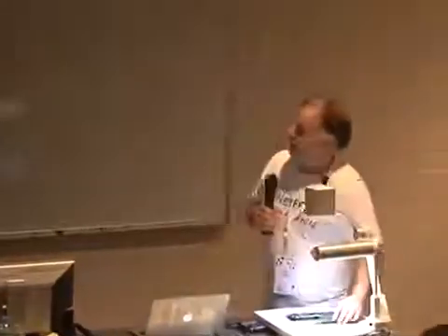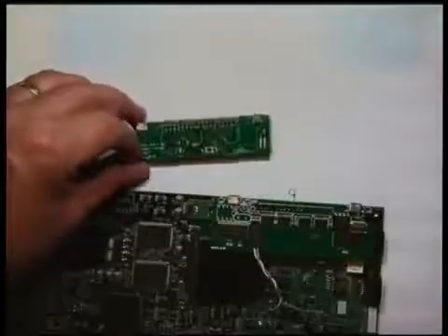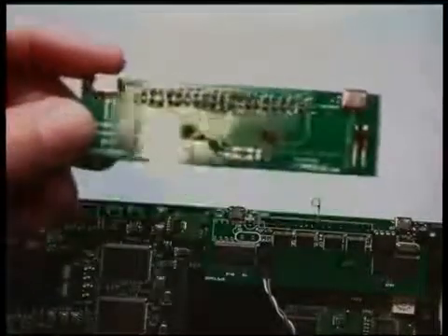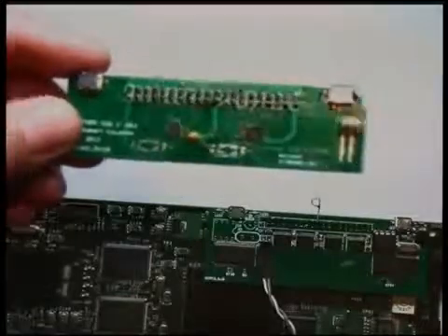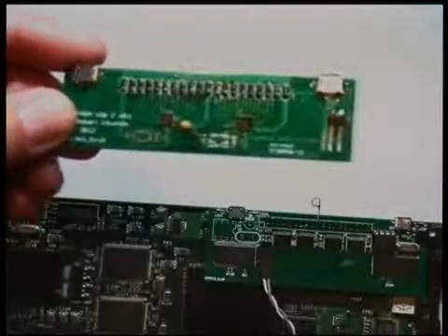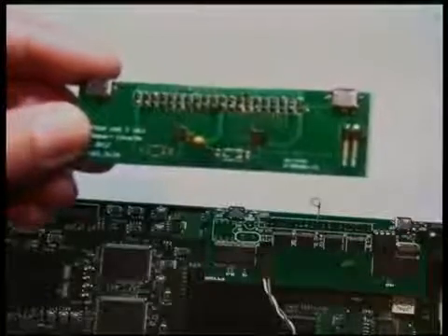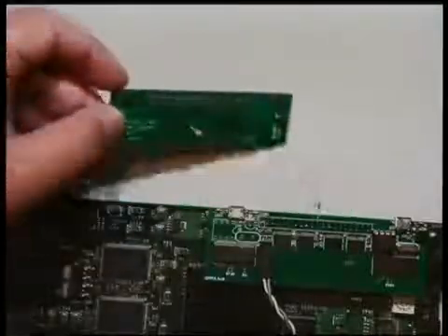So this is the version 0.1 board, and I'll zoom closer in on that. It's got those 2 little tiny surface mount chips there, which we soldered with a hot air gun. All the pins are underneath them. There's no pins, they're just ball grid type things, and the debug connector and the 2 USB interfaces. And I think Bunny touched on the problems with this during his talk.